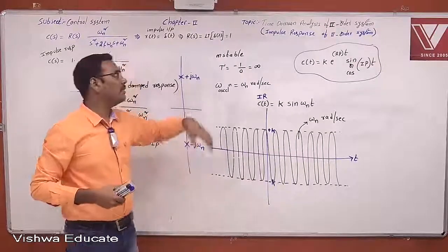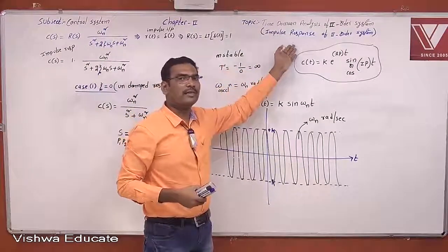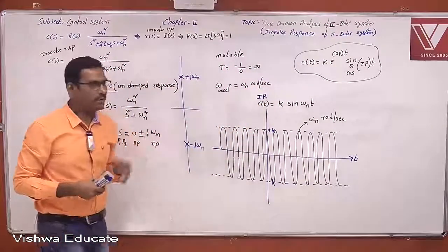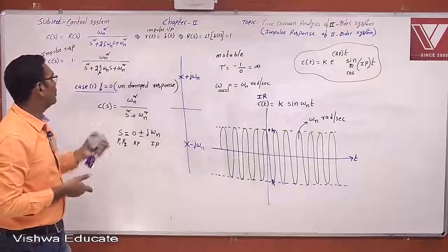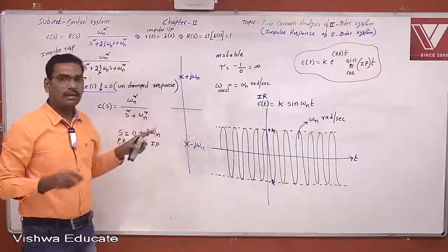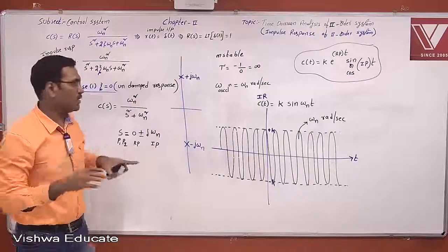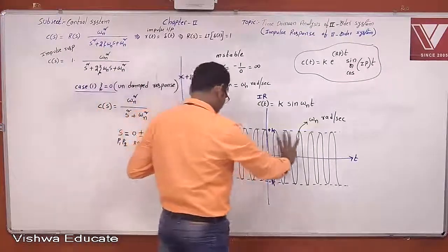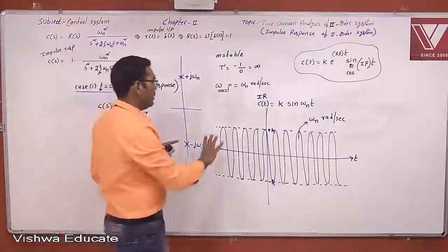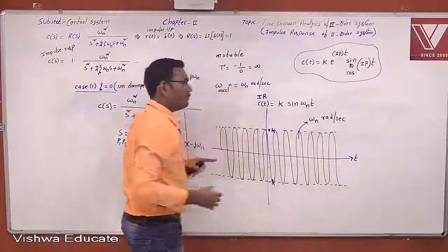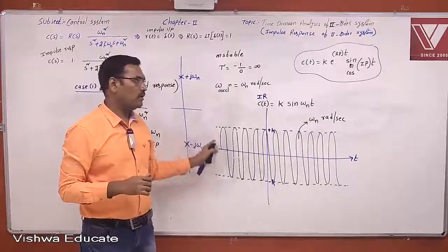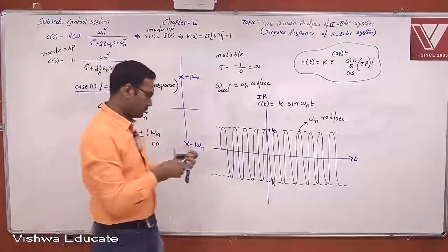We will see again, this is the impulse response, the theoretical response. Again we will put a practical response, where we can eliminate all these delta values. Therefore, when damping factor delta equals 0, this is called an undamped response because we can put the name based on its response. The response maintains constant amplitude and frequency of oscillations. Therefore this response is called an undamped response.